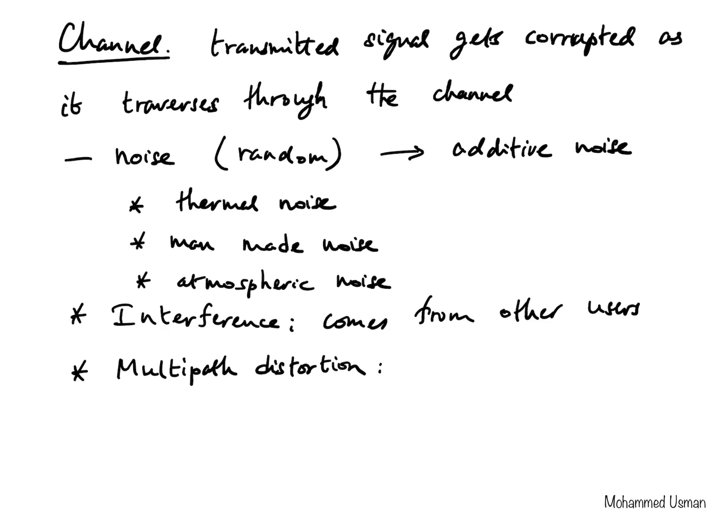The receiver is going to add up those components, and because of the random phase shifts, the added up signal could either add up constructively if the phases are aligned, or it can add up destructively if the phases are not aligned.